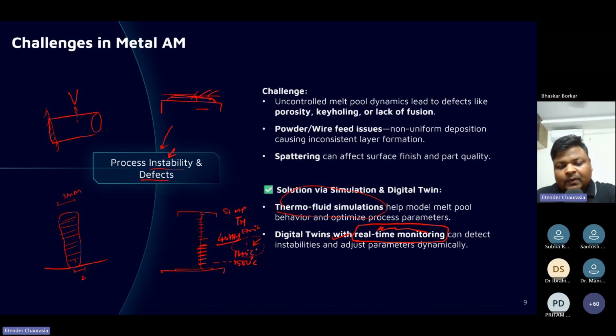Okay, so what we have done is we have used a pyrometer, get the value here, and this pyrometer will send an analog signal to the laser. Okay, this is increased, so it has to come down. So drop the laser, and it will drop, and this all happens within a time of 1 microsecond. Okay, so it will sense as soon as it increases, it will bring it down. As soon as it is brought down, again it becomes, let's say, 1490 or something. Again, it will send the signal. Again, it will increase. So that's how it keeps hunting.